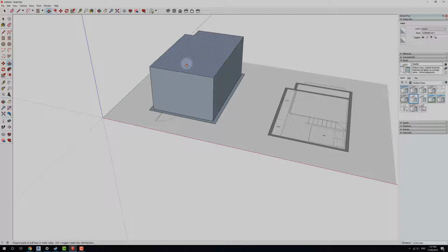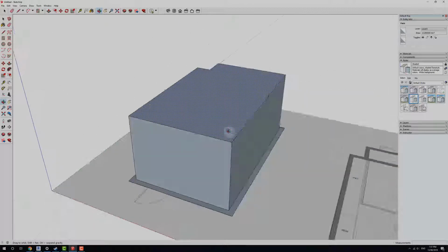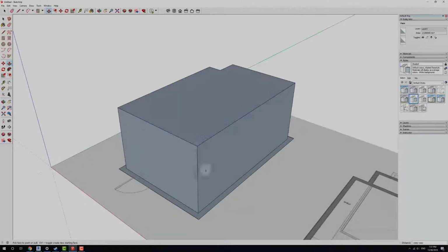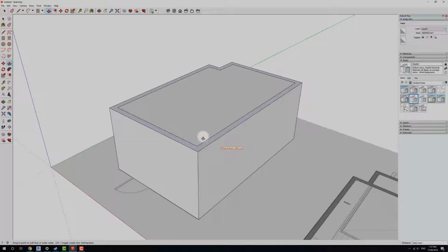So if I model this up, we're basically saying that this shape is inside out, because the blues are visible. So if you get that, you want to double click or triple click, select all the faces, right click and go reverse face. Notice how the whites are now pointing out? That's saying to the 3D modeling software that everything that we're creating is oriented correctly and that it's not turned inside out. Okay, now you notice, oh no, it hasn't changed too much at all. So this here, if we model this up, we've got a nice white shape as well.